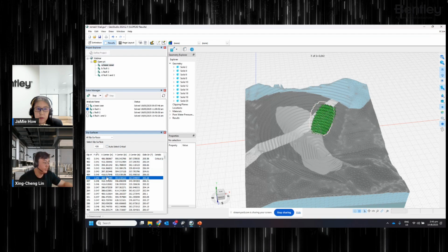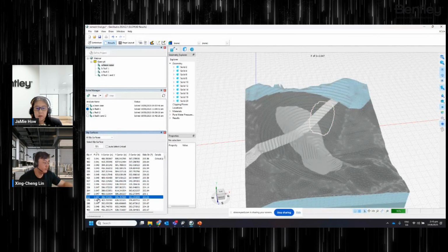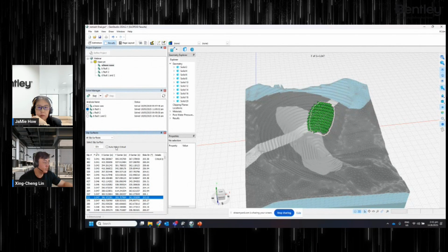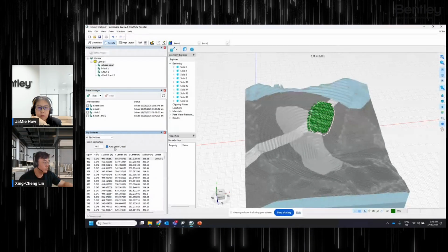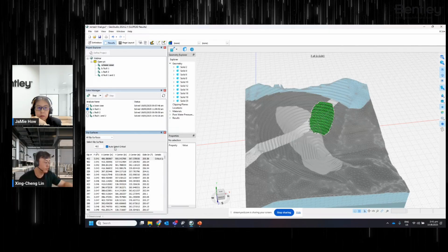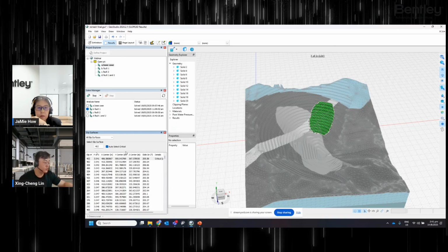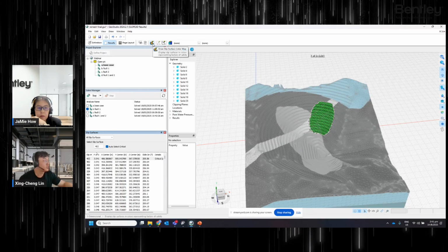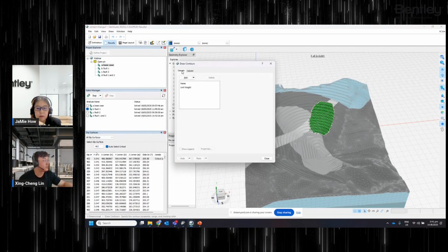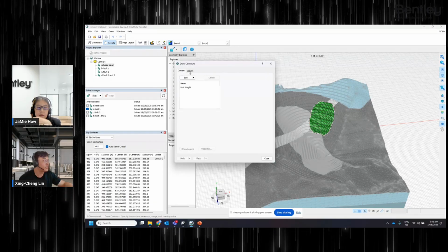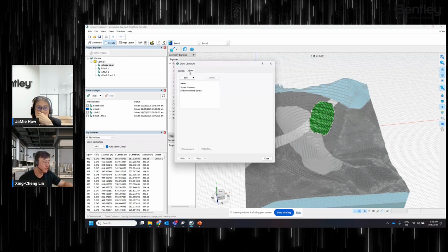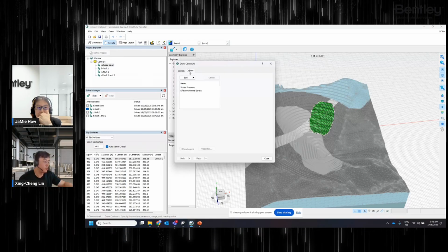we can click and drill down the list to select different slip surfaces. And from the slip surface docking window, I can also toggle this button, auto select critical. And this takes us back to the slip surface with the lowest factor of safety. In the menu bar, there's a draw contours button here. The first tab applies to the entire domain, and the second tab applies to the columns. So you can draw contours either on the entire model domain or on the columns.